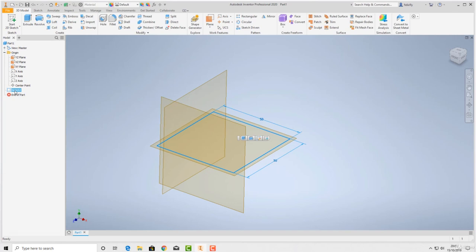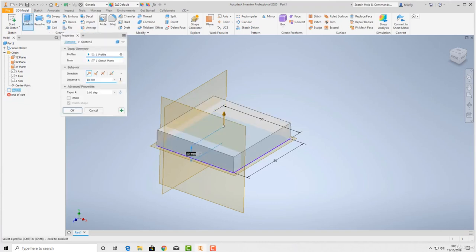So we have our sketch here in the left hand side. I'm now going to click on extrude, so you can follow along here. And what extrude does, as you can probably see, it takes a sketch and it turns it into 3D. Think of extruding something like you used to with the Play-Doh, where it extruded a shape of Play-Doh through a certain stencil. That's extrude. You use it like you would extrude aluminium extrusions or rubber extrusions, that kind of thing. It takes a sketched 2D shape and it brings it out into 3D.